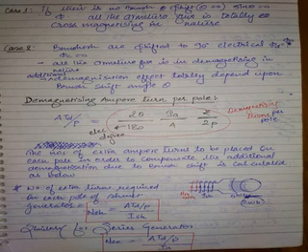No demagnetization means all the armature flux is cross-magnetizing in nature. There is armature flux in the machine. In this armature flux, some part is doing demagnetization, some part is doing cross-magnetization. If there is no brush shift, then all the armature flux is doing cross-magnetization only.